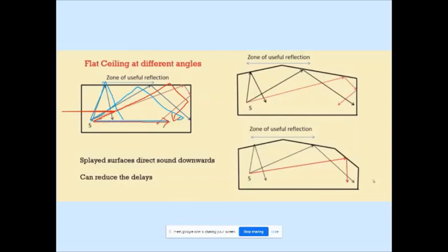If the difference between the reflected path and direct path is more than 17 meters, as we discussed, there will be an echo. So we should avoid this late reflection. What can we do? We can provide some kind of sound absorber somewhere here and on the rear wall to weaken the reflected sound energy. So we can provide sound absorbing material somewhere here and here.